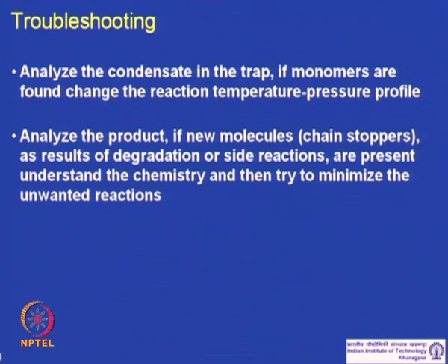That will again reduce the molecular build up, and to tackle this you have to understand what is going on, understand the chemistry behind this side reaction, and then do whatever is the best way to minimize these unwanted reactions. And sometimes the catalyst which you are using in the reaction might be one source which is catalyzing the side reactions as well. So, you might consider changing the catalyst or even reducing the catalyst amount in the reaction, so that your side reactions come down as low as possible.